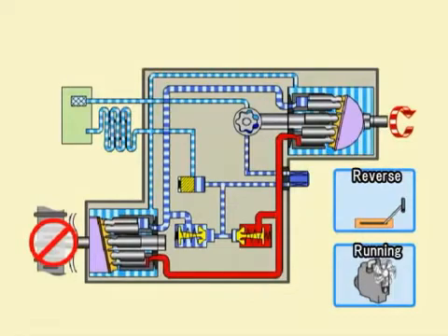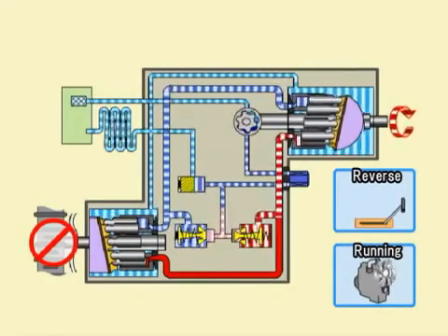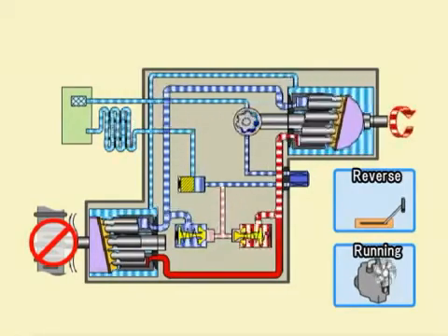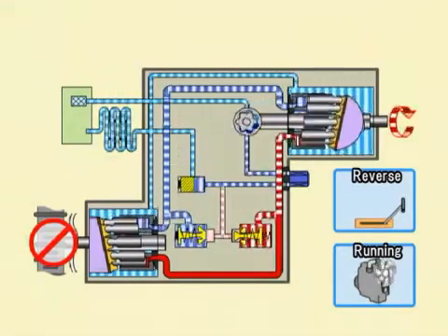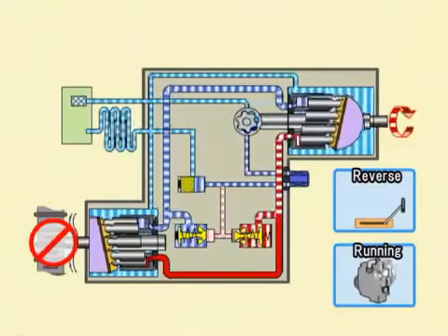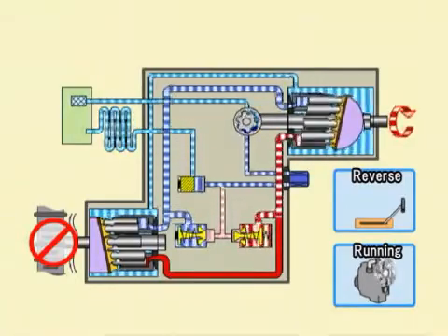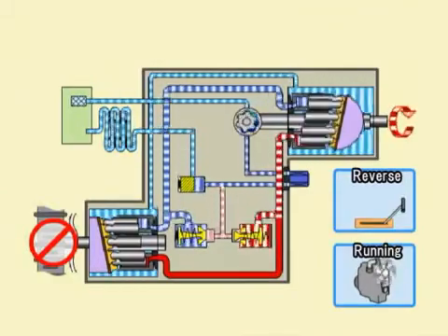Now let's suppose that the traveling part of the machine locks up due to an external factor and stops rotating. At that time, the pressure in the oil circuit reaches its maximum value, but the pistons on the motor side can't move. With the speed change lever still in the same position, the pistons on the pump side continue receiving power from the engine and continue pumping oil. Finally, the powerful spring of the check and high-pressure relief valve is depressed by the overwhelmingly high internal oil pressure. The poppet moves to the left, and high-pressure oil spurts out to the left, preventing damage to the HST. When the high-pressure relief valve opens, the output shaft on the motor side stops rotating.